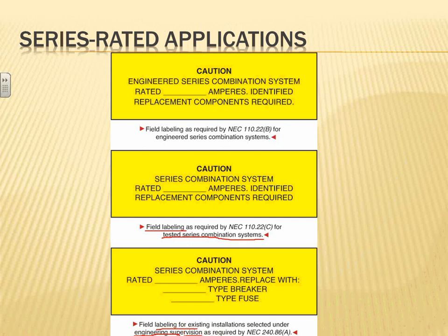Great, because they're cheaper. There's a sheet I didn't copy here comparing a 22,000 amp interrupting rating circuit breaker to a 10,000 amp, and you can see the difference is substantial. Two times, sometimes three times more expensive, the same circuit breaker with higher interrupting.